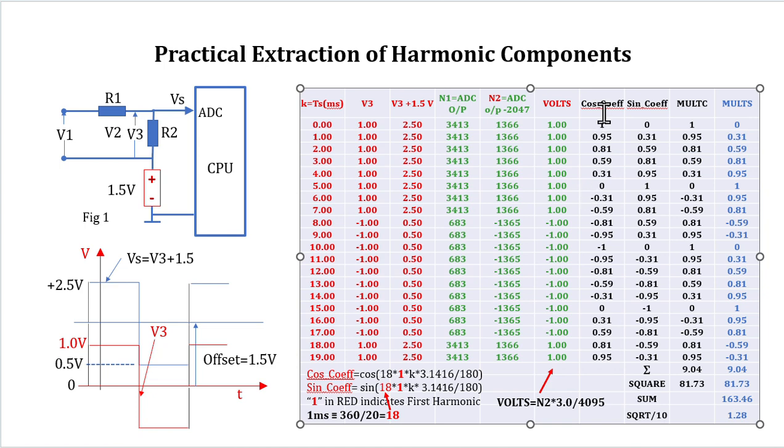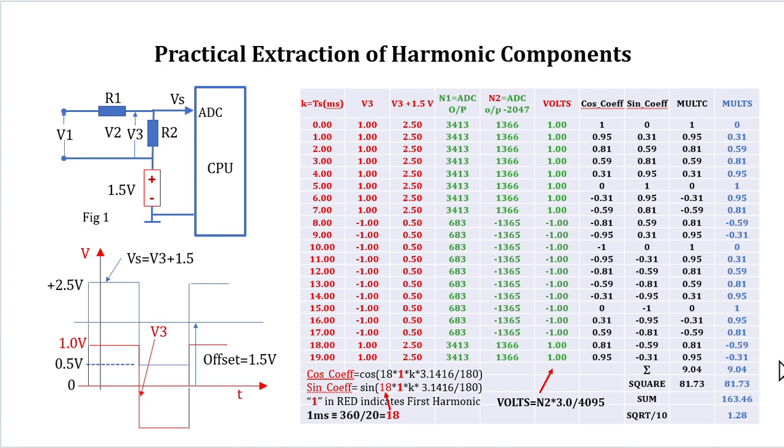You are not trying to obtain it from any software procedure. This is standard. So you form 2 arrays for every harmonic and store those arrays in the memory of the microcontroller.